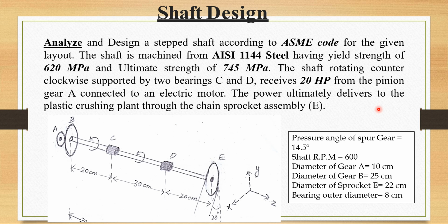In the class, I had flipped those forces. Yes, there will be a slight difference in the diameter, but in the problems, please do correct the triangles. In the gear triangles, the component going tangentially will be WT, and the component applied radially will be WR, and the rest of the calculation will be the same.